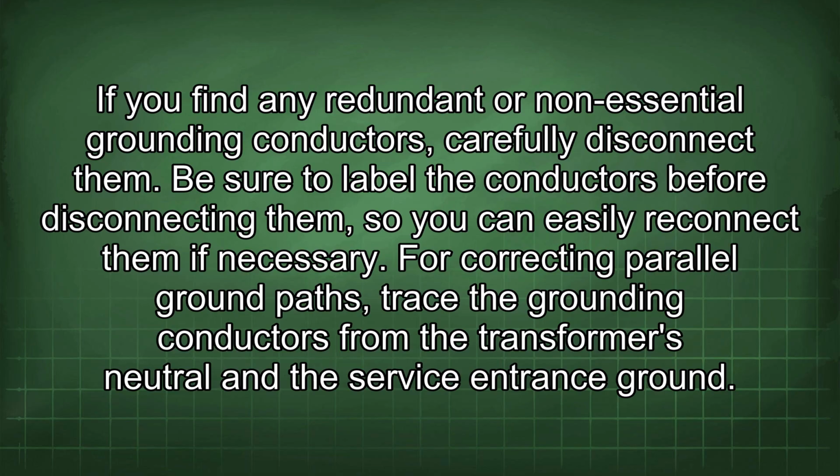If you find any redundant or non-essential grounding conductors, carefully disconnect them. Be sure to label the conductors before disconnecting them, so you can easily reconnect them if necessary.